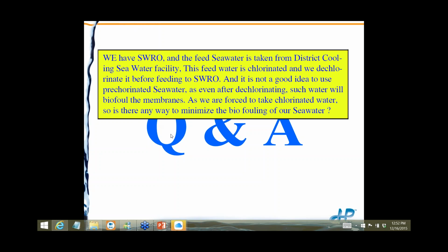Scale inhibitor, we've done a couple of research projects where we did a bio count all around a water treatment system, and the scale inhibitor tank had absolutely the highest number of bacteria. But that's only in dilute. If you're pumping full strength, you don't have to worry about it.